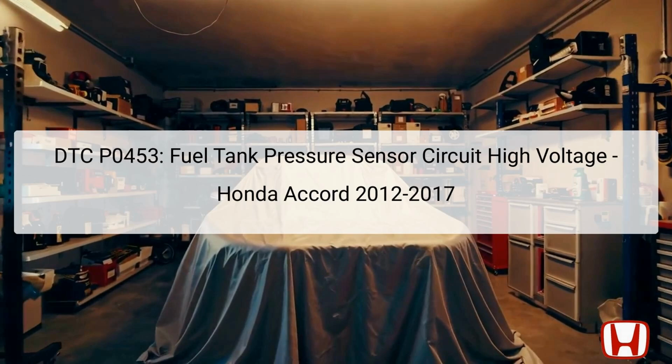This presentation focuses on DTC P0453, which indicates a high voltage issue in the fuel tank pressure (FTP) sensor circuit. The DTC is relevant for 2012 to 2017 Honda Accord vehicles equipped with the K24W1 engine type. The FTP sensor plays a crucial role in the evaporative emission (EVAP) system, which is responsible for detecting leaks in the fuel system and maintaining optimal fuel vapor levels.